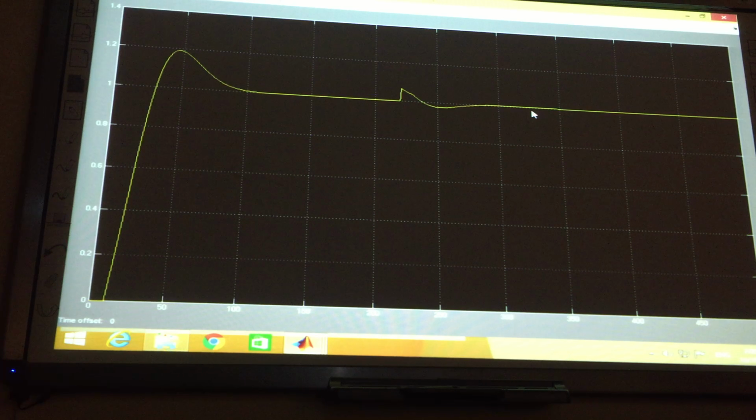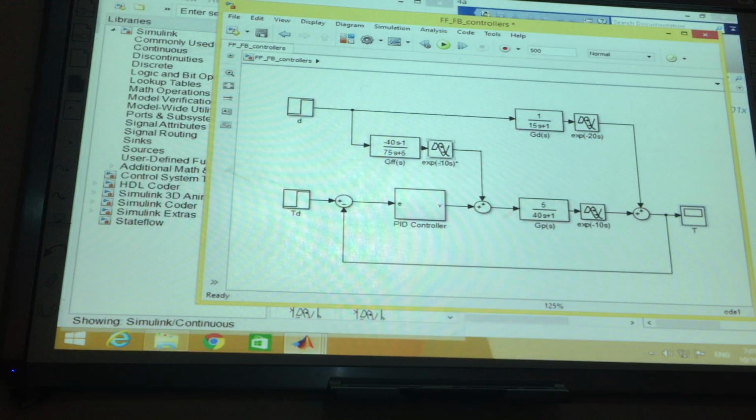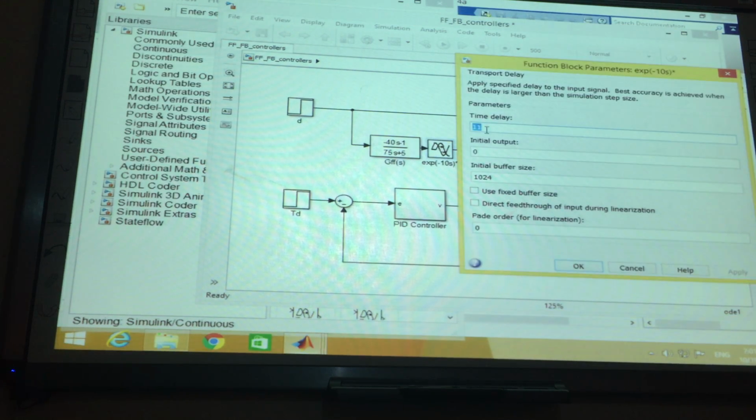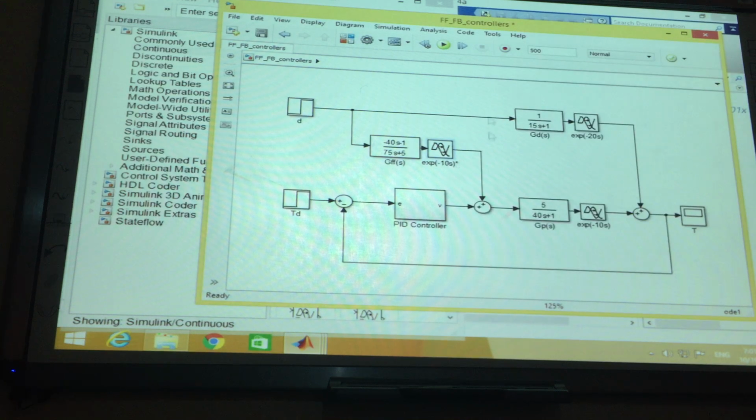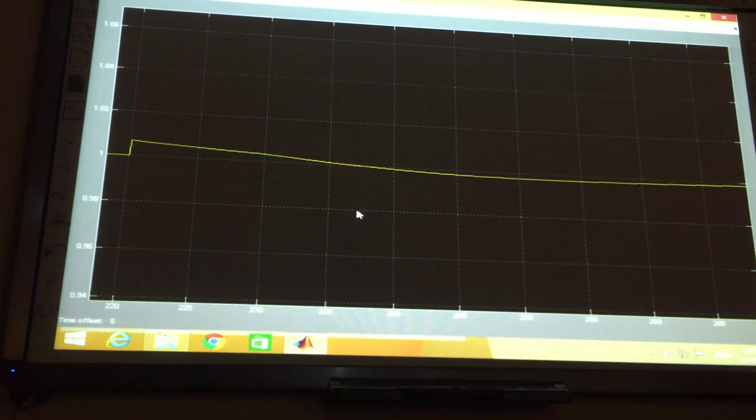Okay, guys? But this is also, we'll go back to your question, Walid. If we have a very good sensor, it will get rid of the effect of the measured disturbance. But if you have a very bad sensor, and it will take, let's say, 1 second, look at this, you will suffer again from, let's say, around 80 or 60 seconds delay of not maintaining the same temperature. So that's why this one, it could be 10.1. If it's 10.1, maybe I will have just a small glitch, which is 0.1 for the sensor. Look at this. Okay, guys?